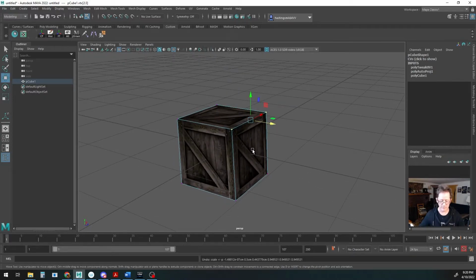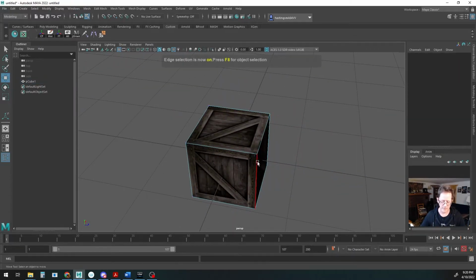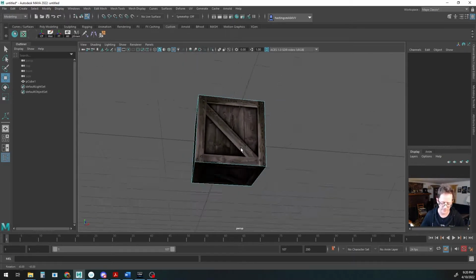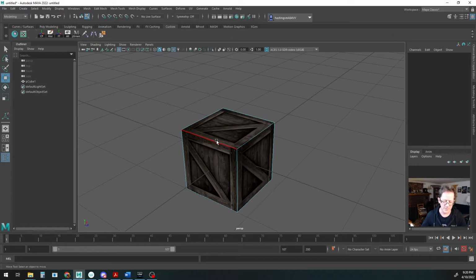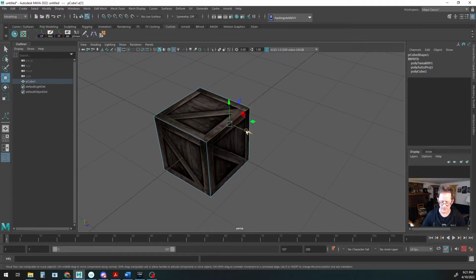And undo that. Now edge mode, if we press F10, what I often suggest is having a little sticker next to your keyboard, or on your keyboard, that shows the different F8, F9, F10, F11. I have a nice PDF that also shows all the key commands. So edge mode, as you can see here, these are all edges. If I hover over one of these edges, it becomes highlighted. If I click on this edge, you see that the gizmo is right in the middle.